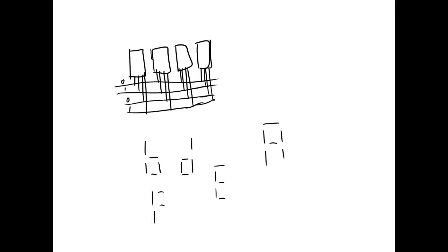So I've seen these things used as a hex decoder before, but you have to learn those patterns, right? You understand? But we have a decoder. It's a 9368. That'll give you all these characters. It'll do hex. So it'll do 0 through 9, then it'll do an A, B, C. I don't remember if it does a lowercase c or an uppercase C. I'd have to dial it back out. So it can do an A, B, C, and D.